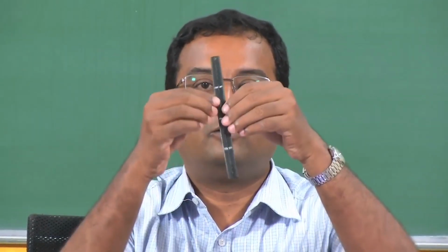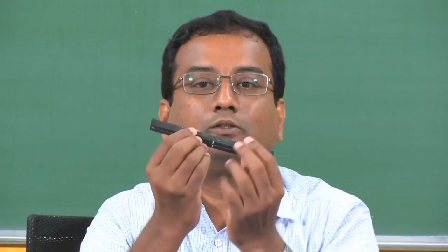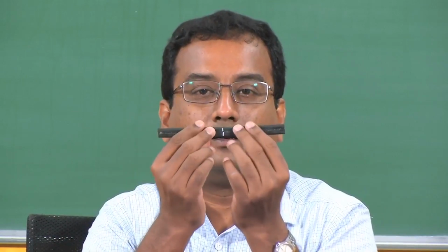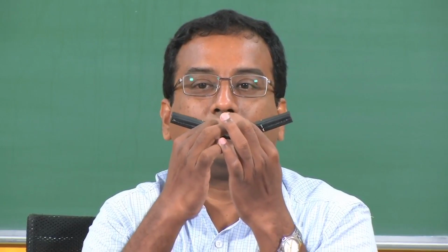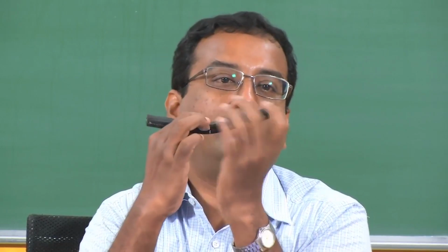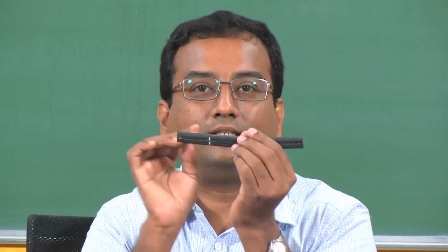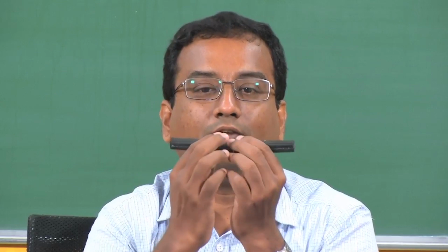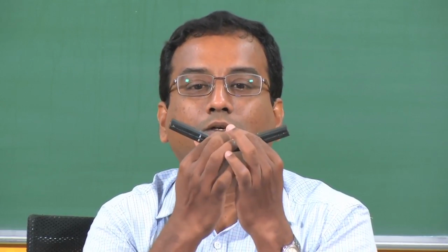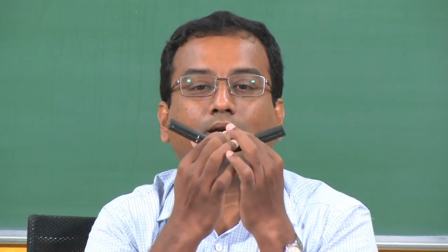On the other hand, if I take glued rubber blocks of the same size, but glued here, you can see I can't separate them out. So, now let us see what happens if I bend it. The straight line remains straight, the edges remain parallel here, they are not going zigzag, because the glue is resisting the shear stress that is developing at that interface, and hence it is able to do this. And this one is much stiffer to bend compared to the other block, which is much more flexible.